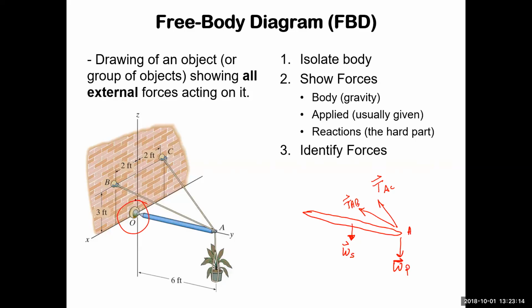So there are 3 unknown forces, and you have to sort of reason your way. And there is a cheat sheet or a table of all the reactions that these joints can actually apply on a body. But we can see that we're probably going to have an FOY that's going to be pushing out to counter the tension of the cables pushing it in. We might have an FOZ here pulling it up, most likely, and maybe if there's an imbalance on the cables, an FOX.